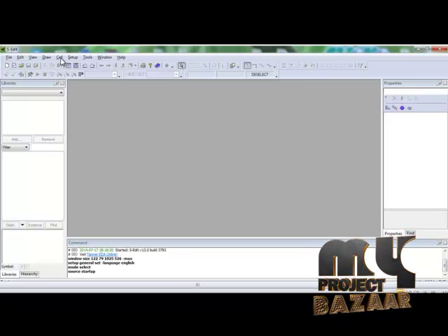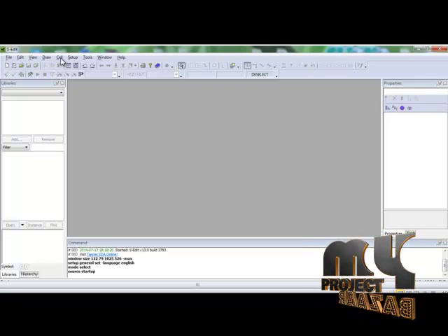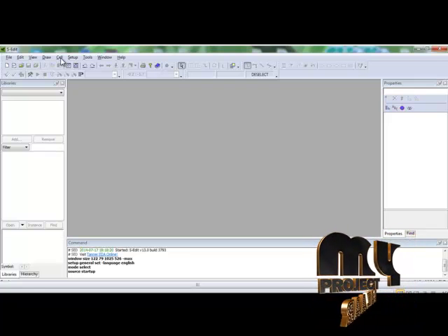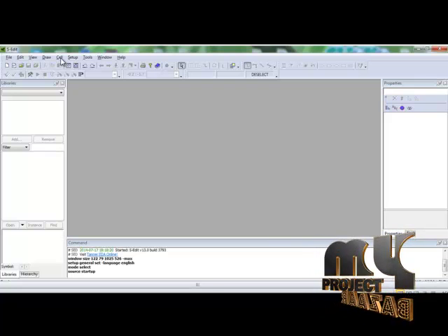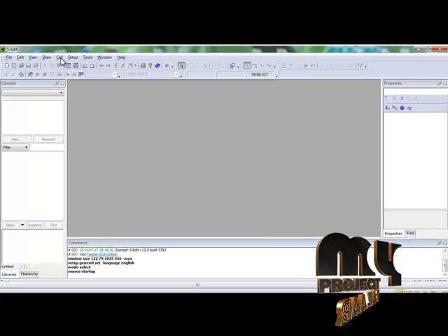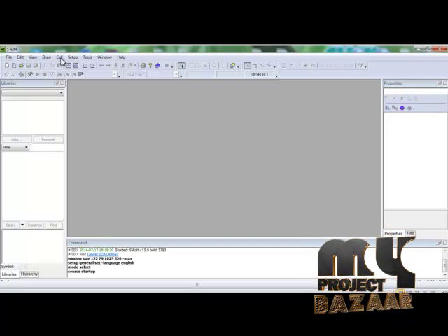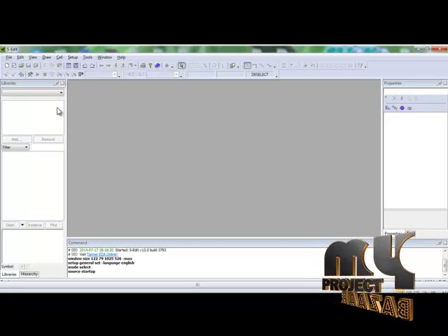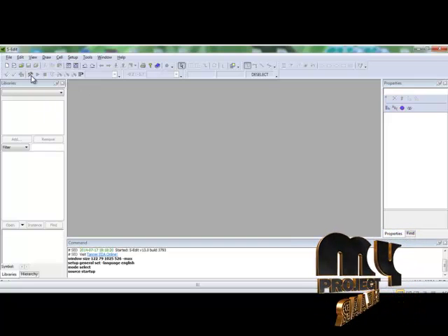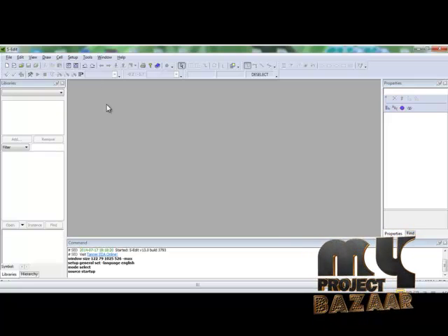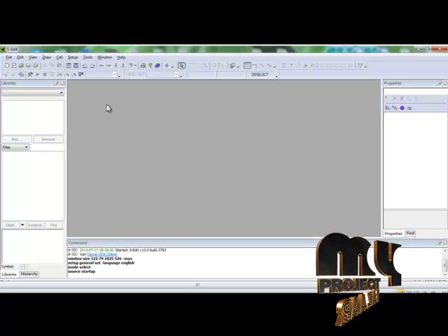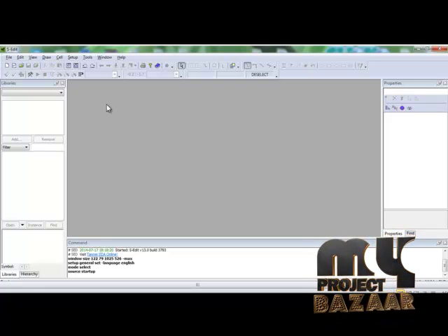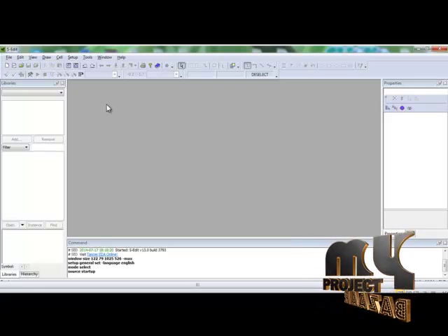In the cell, we can include a lot of libraries which consist of transistors, CMOS transistors, resistors, capacitors, such general devices. After designing, we have to set up the simulation. After that, we have to save the file and execute it. If we execute the circuit in the correct manner, we can get the output in W-Edit.